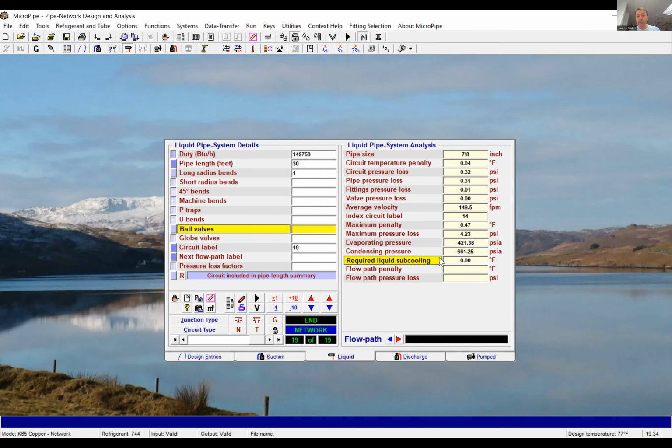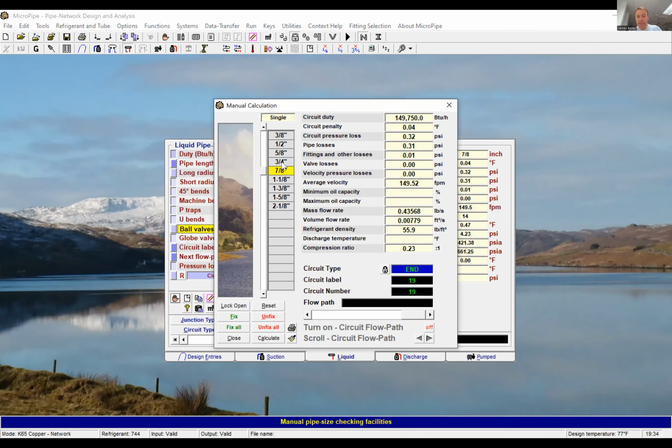Naturally, what it's going to do there is reduce the velocity in feet per minute in this instance and reduce the penalty. But with this little hand size here, we can actually use this without any interference. So we can say at 3/4 we're up at 204 feet per minute. Let's see what it says at 5/8. I think it's going to accept it at 5/8, but we're up at a higher velocity there.